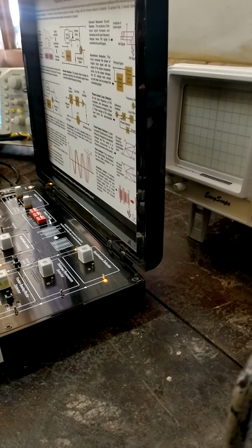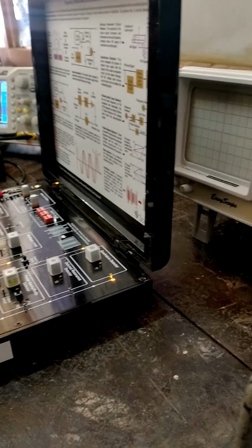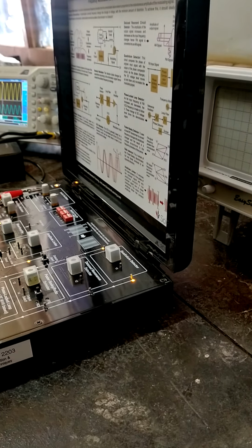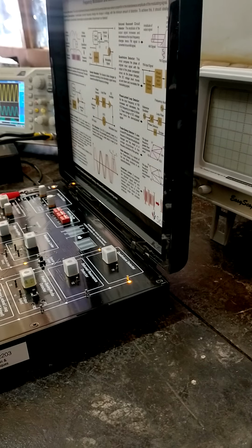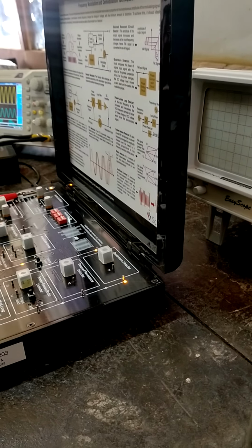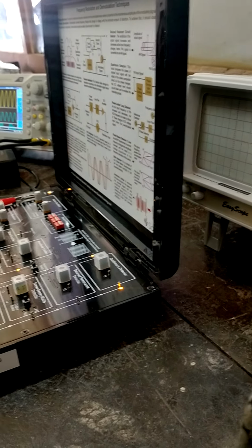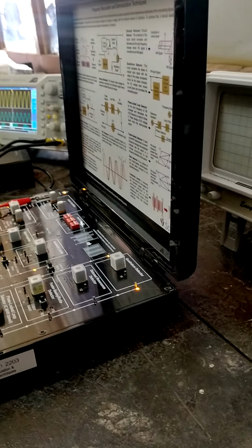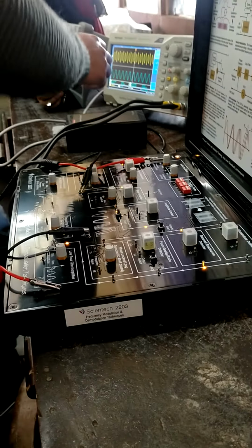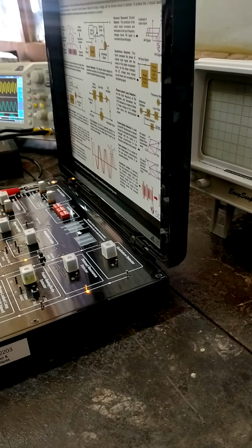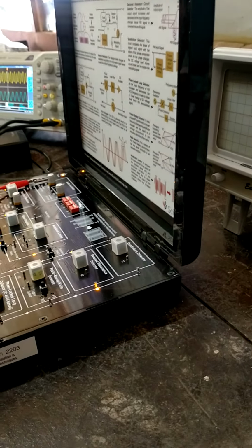Now you will measure the amplitude and the frequency of the received signal, and notice that the frequency of the received signal must be equal to the given message signal frequency, like you are doing in the AM reception experiment. You will do the same thing. Now you will change your detector to another detector and notice the change in the amplitude and the frequency.